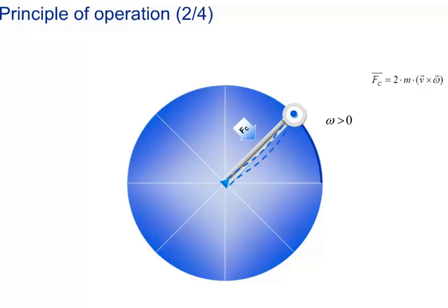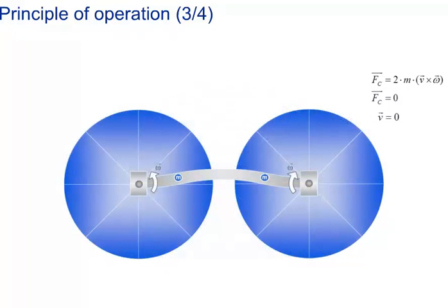This basic idea was the foundation principle of the first Coriolis meters, using a tube rotating 360 degrees, slightly distorted by the Coriolis forces, with the degree of distortion being measured. However, since 360-degree tube rotation is quite impractical, more practical methods of harnessing the Coriolis force were soon developed. The solution was a tube oscillating up and down and not performing a complete 360-degree rotation.